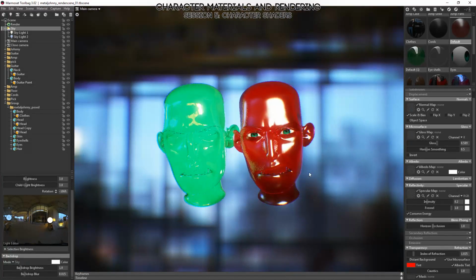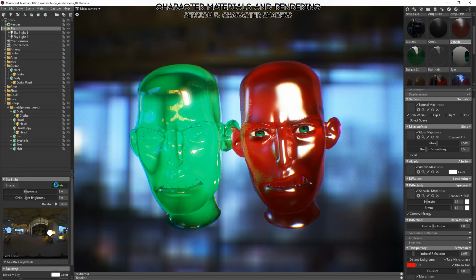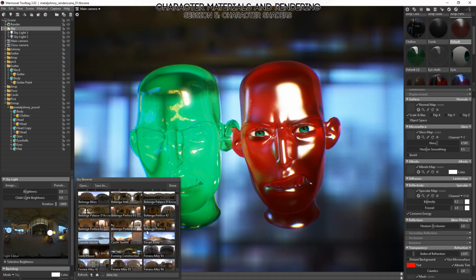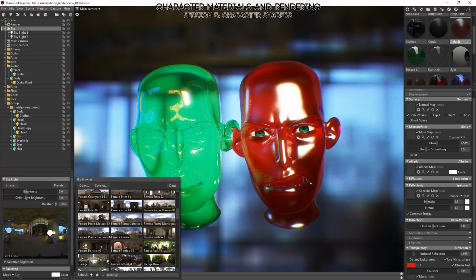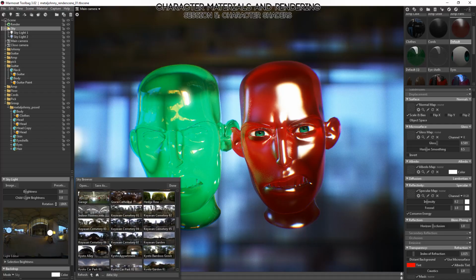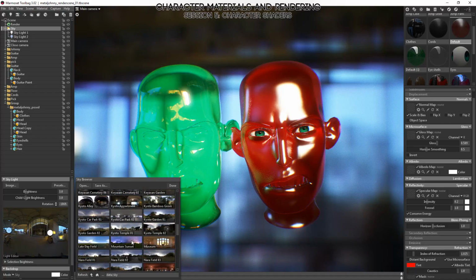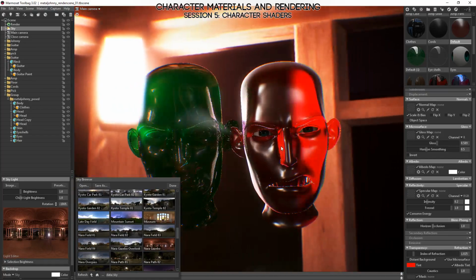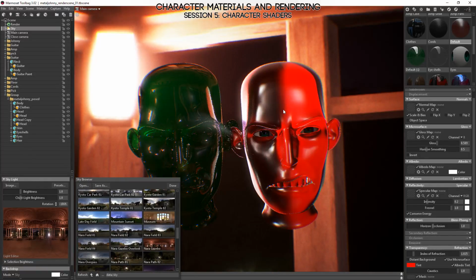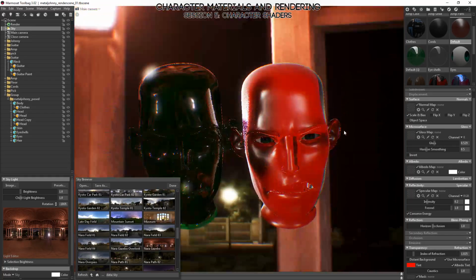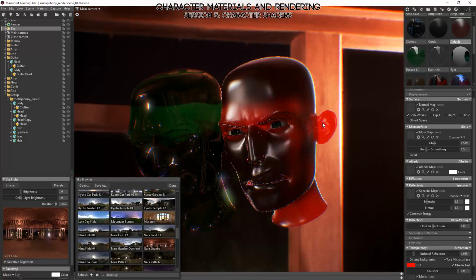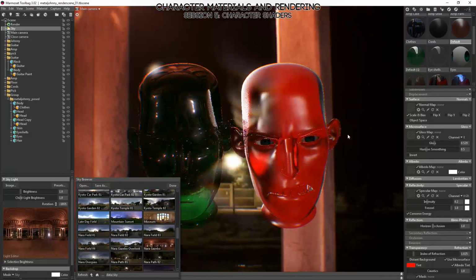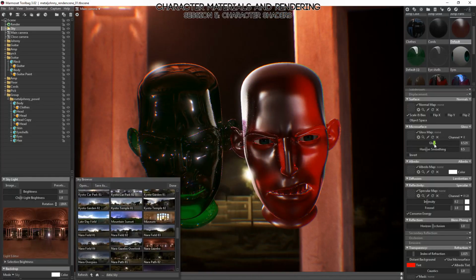Okay. And we'll change this to a different preset that's a little bit better for our purposes. Let's just change it to, oh, what's a good one? Here we go. This is a good one. Has lots of contrast in it. So you'll notice when looking through this red head that as I turn up or lower the gloss, it actually starts to look more and more like frosted glass. It blurs what's behind it, and it also blurs the reflections, the specular reflections, a corresponding amount.